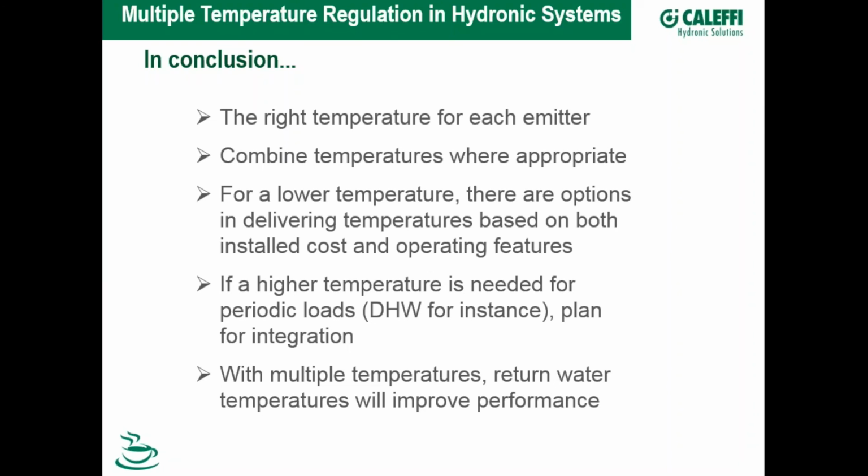My preferred strategy really doesn't come back to whether the boiler is running continuously off of a TT contact. It's about outdoor reset and finding the lowest outdoor reset curve possible. So if I am using an end switch to bring the boiler on, my goal is to keep that end switch closed 60 minutes out of every hour.